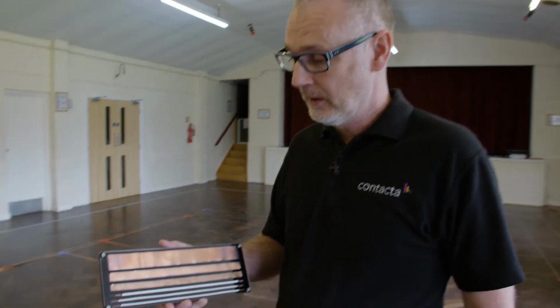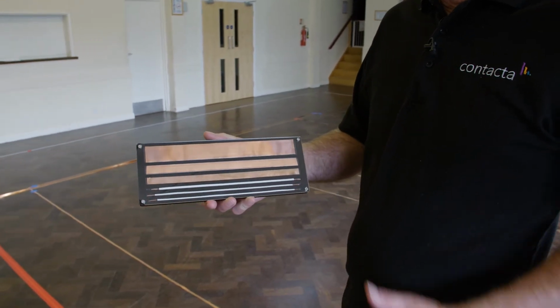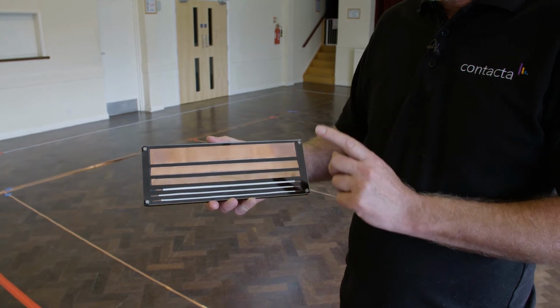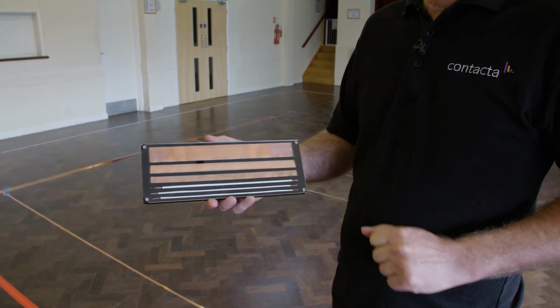Once a survey has been completed and it's been decided that an installation of a loop system can go ahead, we then need to choose the correct cable for the installation. There are various cables available. There's flat copper tape, there's round wire, and there's also direct burial cable, which is also a round wire, but it has a special coating to protect it against the alkalines in concrete, etc.